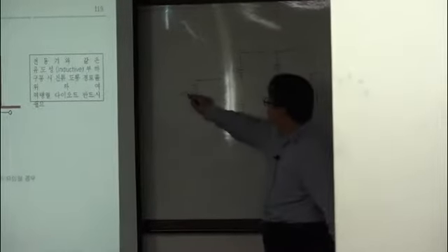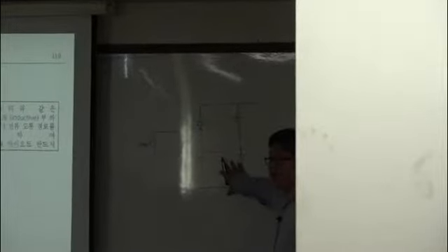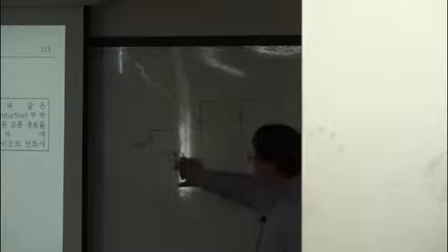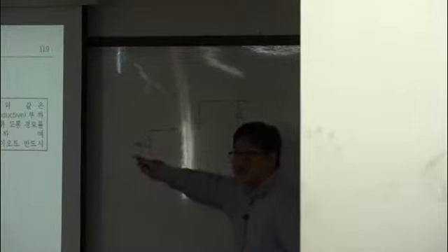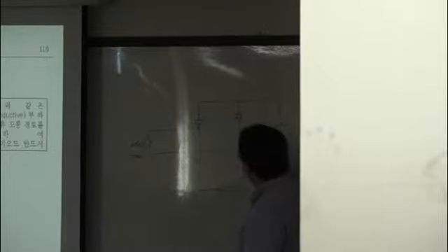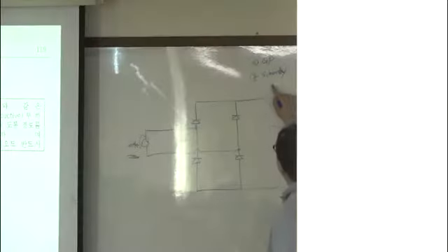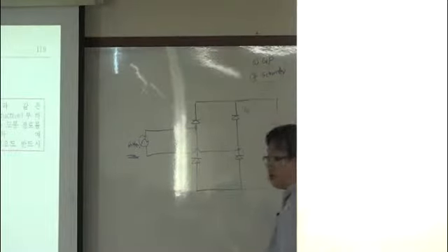You have 60 hertz here. Yes, full bridge rectifier. The operating frequency of this full bridge rectifier is just 60 hertz. This is a low frequency, right? Then for this diode, you have, for example, general purpose diode and Schottky. Which one is suitable here? General purpose. Why?